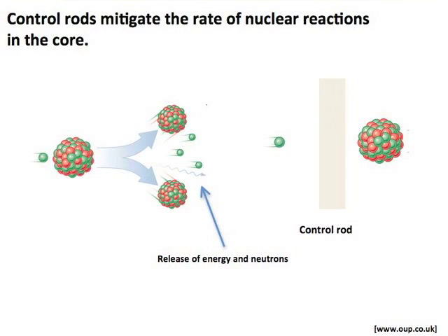Nuclear power comes from obtaining fission. Fission is caused by a small neutron hitting a relatively large atom, causing it to split up, releasing more neutrons and a lot of energy. Now, this process, again, releases a lot of energy. In order to control this energy, we use control rods, which, by definition, according to Lamarche and Barada, are movable pieces of neutron-absorbing material. Here, you can see the neutron going towards the atom, and the control rod will eventually block its path and absorb it.